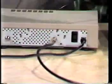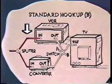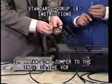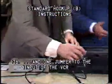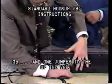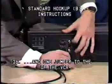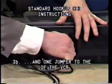Oh, that looks good. Now we want to take a second jumper, John, and connect it from the other side of the two-way splitter. And we want to hook that to the input of the VCR. Okay, the other side of the splitter out to the input of the VCR. Now here's something to keep in mind too. On the back of the video cassette recorder, we're going to the VHF inputs and not the UHF, and that the in might be on top in some models, it might be on the bottom in the other, but we're going to the input of the VCR.